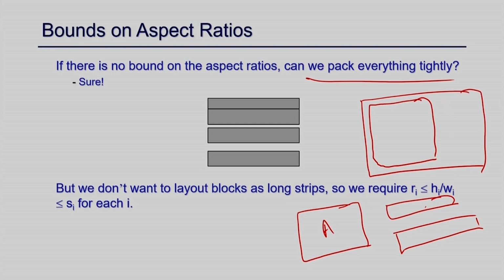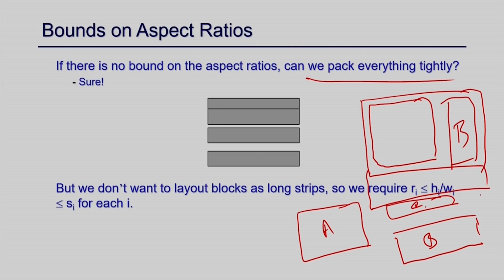If you place one of them here, say this block is something like this, their length is more than this, so they cannot be placed this way. Suppose this is B, and I place it this way. Now there is no way to place C, because everything is fixed and there is no place. Then basically you have to increase the area of your design, the chip area, just to place C here, and a lot of space remains vacant.